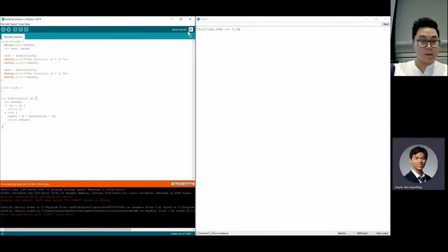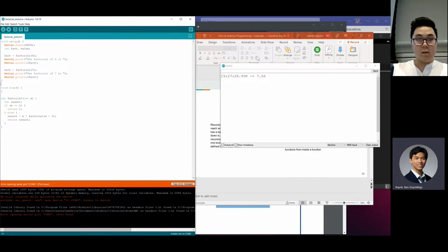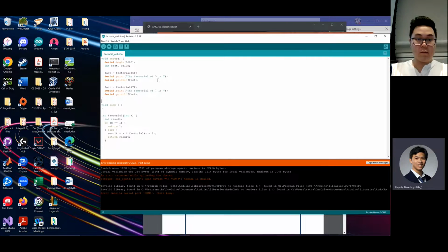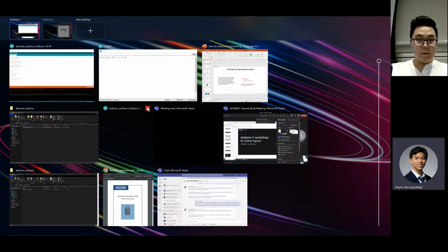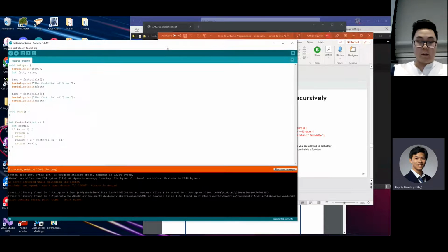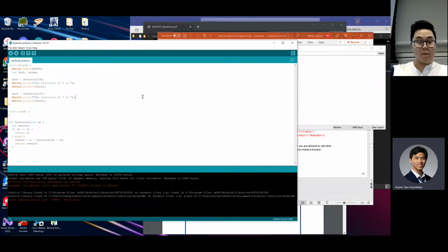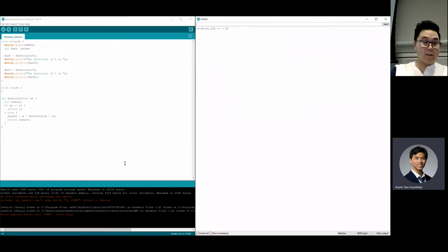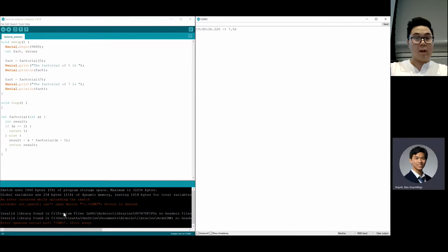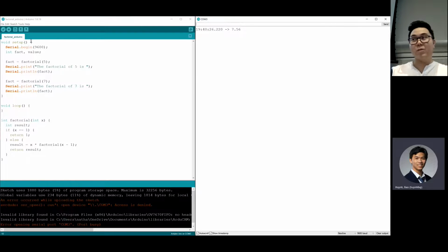Access denied. Why is access denied? COM3 port busy. Oh no. But yeah, the interesting thing about Arduino is that you can't have two Arduino things occurring at the same time, and so you'll get the same error that I just did, where it says the port is busy. That means that one of the things is still technically running and stored on the Arduino. And so you have to store everything at once on the Arduino, which sometimes makes things very long.